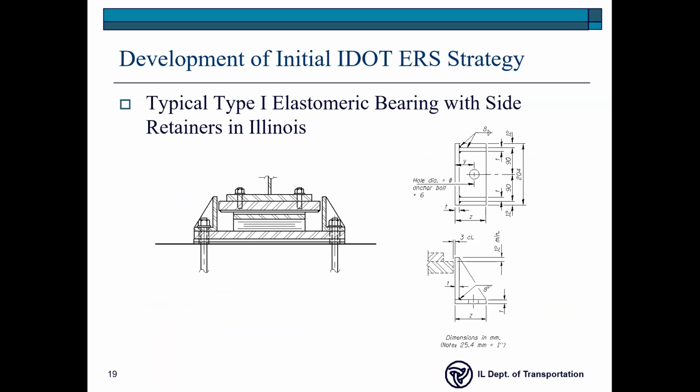These are really our support conditions. Our bearings really approximate either a pinned connection or a fixed connection. When we talk about a fixed connection in a bridge, it is not what you typically think of from what you learned in school from basic structural analysis. We think of a fixed connection as being able to rotate, but it can't move sideways back and forth. And a pin connection is a pin connection. It can rotate, and it can move back and forth.